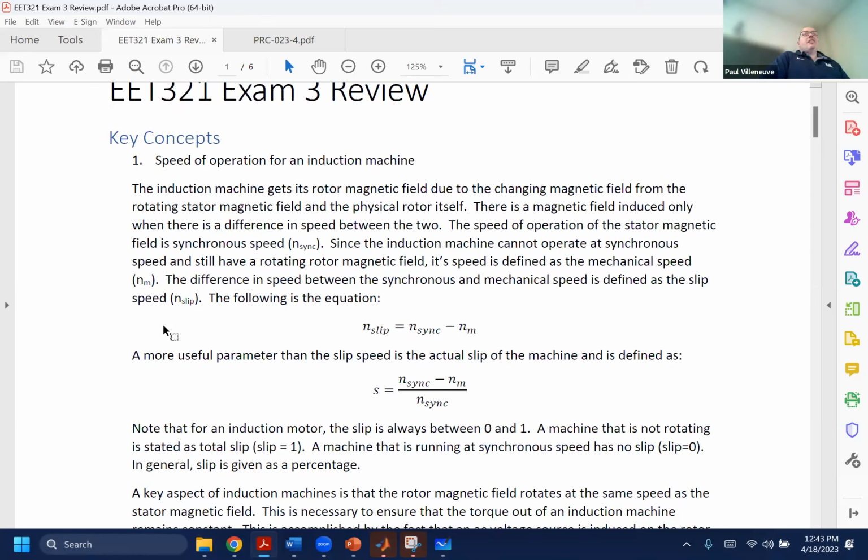That current is AC, and its frequency is going to be whatever it needs to be to make up the difference in speed, because that AC frequency that we have on the rotor is going to cause a magnetic field to spin at whatever that equivalent synchronous speed is. And the difference in speed between actual mechanical speed and synchronous speed is the equivalent electrical frequency.